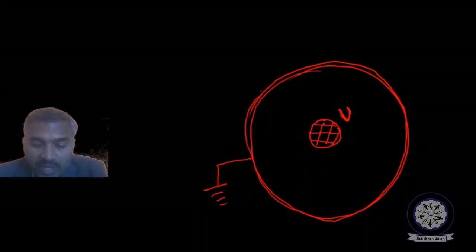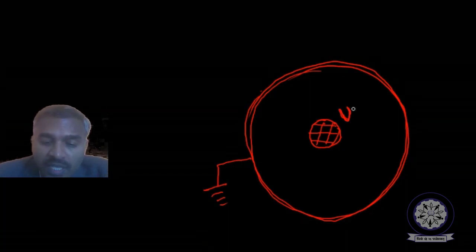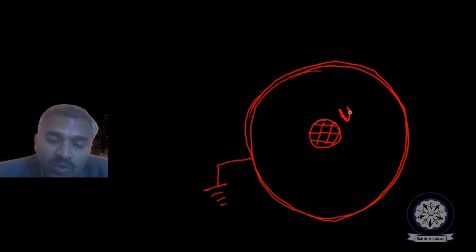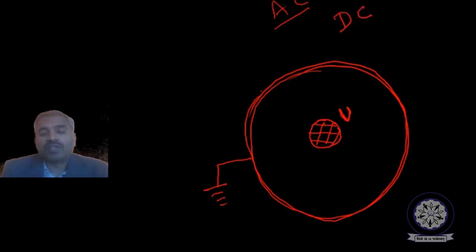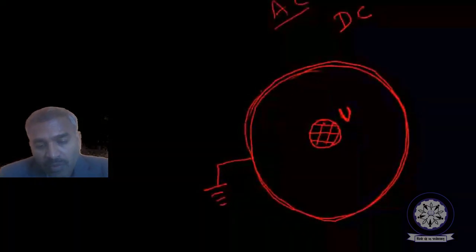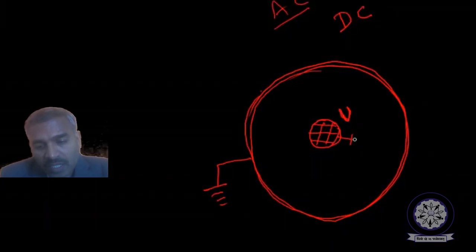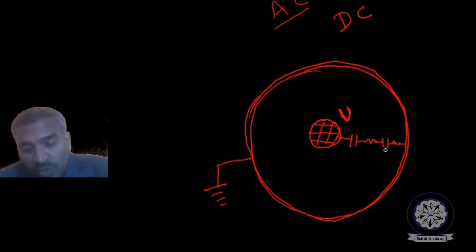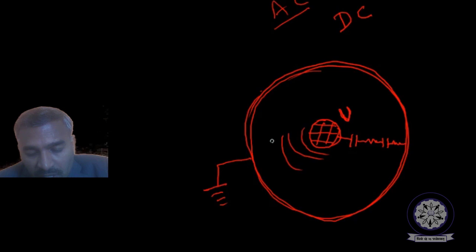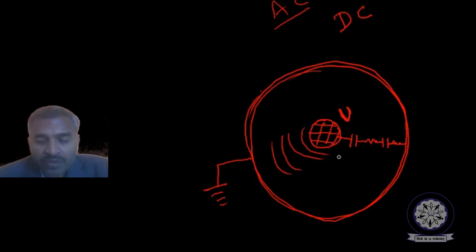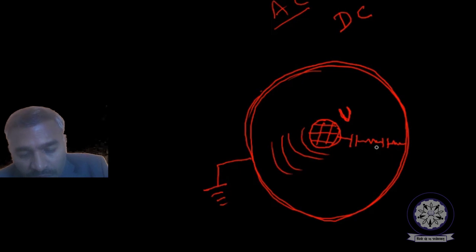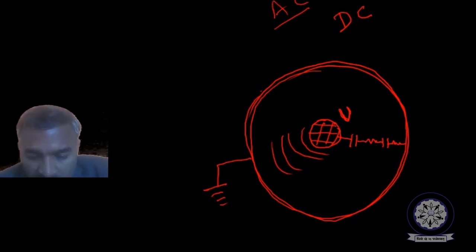So what I mean to say is that for the AC case and the DC case, the two extreme circuits whatever are given are suitable. DC case: if you represent all the dielectric material by only series capacitance and resistance, like this. I am drawing only 2 here. Actually around 100 such units, each layer like this is represented by one capacitor and one resistor. So 40 to 50 or 100, one of my students is working on this actually.